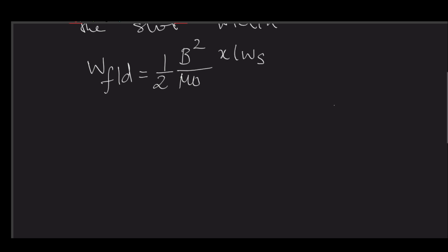So what we can do here is that instead of directly finding the force, we can start with finding the expression of that energy, which is half B square by mu naught, or you can write it like Bs to clearly indicate it is the slot flux density. So what you will get here is a very simple thing, you will get this value.